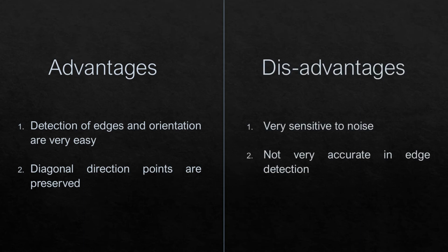The disadvantage is that it is very sensitive to noise. As you saw in the previous images, it was hard to believe the Roberts detection. It was detecting those particular values that were not even edges, and where there were edges, the detection mechanism was not working on it. Since it's highly susceptible to noise, it's not very accurate. A lot of the images that we get aren't completely noiseless, and work best with discretely formed edges which can be easily detected.